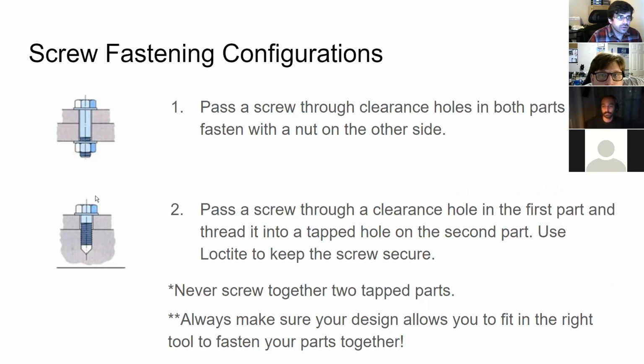If you do case number 2, where you do not have those nylock nuts, we'll use something called Loctite, which is a thread locker. We'll put it on the screw, and for metal, not plastic, for metal, it will basically dry as a solid nylon and keeps your parts from vibrating apart.